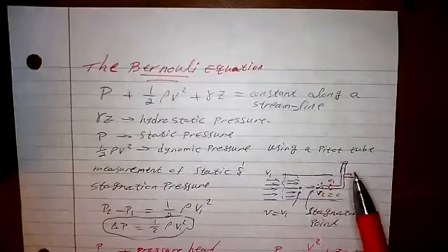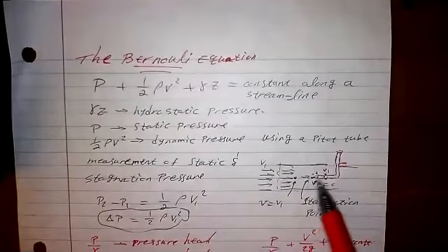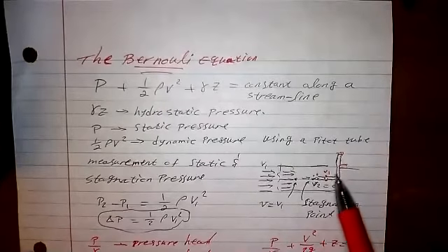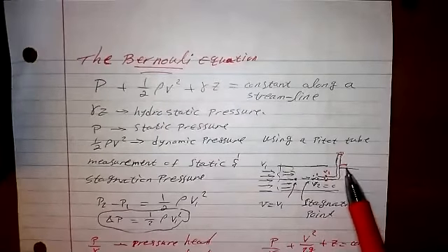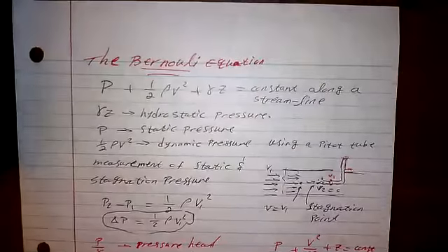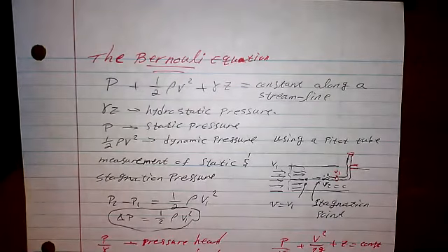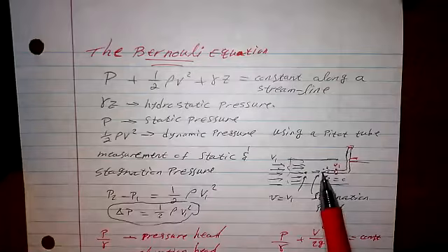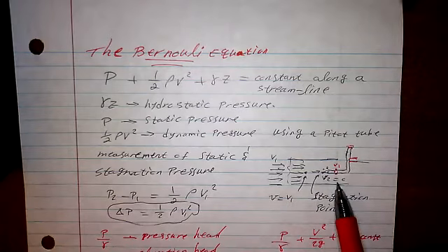That's a very nice device. It looks like this. It's an L-shaped device, and it has a cylindrical body with a port here, which we can connect to a U-tube manometer assembly. So we can have an inclined manometer assembly in the laboratory setting. You can determine the difference in pressure, which is the stagnation pressure. That's a stagnation point. At that point, the velocity is 0.